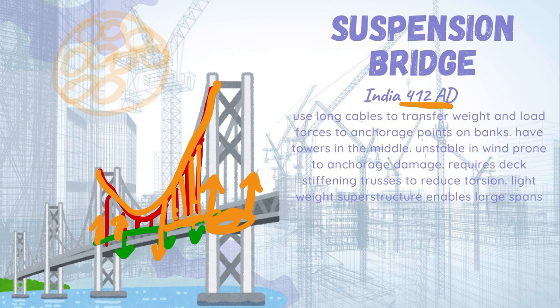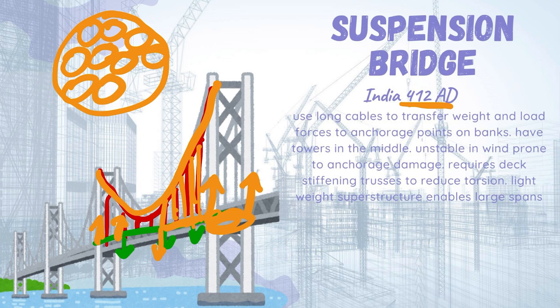Suspension bridges can cover the largest spans, and they are often made out of steel, and the cables are primarily made up of smaller steel cables woven together. So a traditional cable in the suspension bridge might look like this on the outside, if you're taking a cross section, but inside it might have 9 individual little cables, and all these cables combined will be intertwined to help give it more strength.